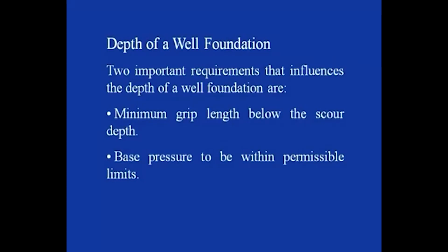So, while deciding the depth of the well foundation, these two criteria have to be kept in mind, and both of these have to be satisfied. That is, the minimum grip length below the scour level has to be provided, and whatever base pressure is coming because of the soil should be within the permissible limit.